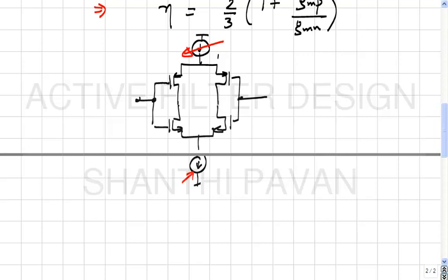And this is a general principle in circuit design, right? If there are devices in the signal path which do not push signal current, but only add noise, then the excess noise factor is bound to increase on account of these devices.